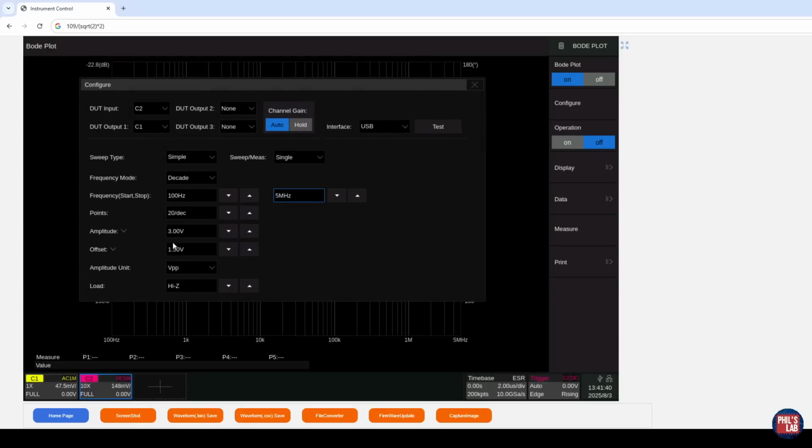Now, of course, the actual transfer function, the actual output magnitude doesn't terribly mean very much because my input signal is that of the function generator, which is controlling the FET, which is controlling the current. And my output signal is essentially the average of the RMS magnitude measured at the output by this Bode tool. But hopefully we can see that the curve that is traced out follows our PDN impedance profile that we measured early on using the vector network analyzer.